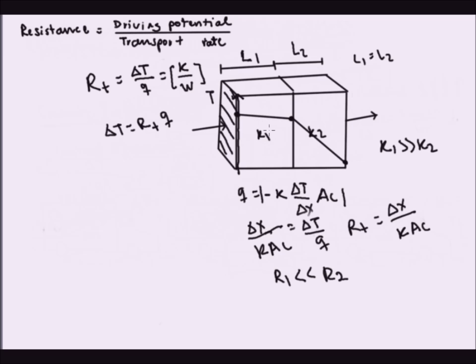And so we can see here that from the resistances, we can have a feeling of how our temperature profiles will look. Okay, so the second case is for when you have a surface exposed to a fluid. So when you have a convection heat rate, and this would be Ts or T surface. And so the expression relating the temperature difference with the heat rate is just Newton's law of cooling, or the convection heat rate.